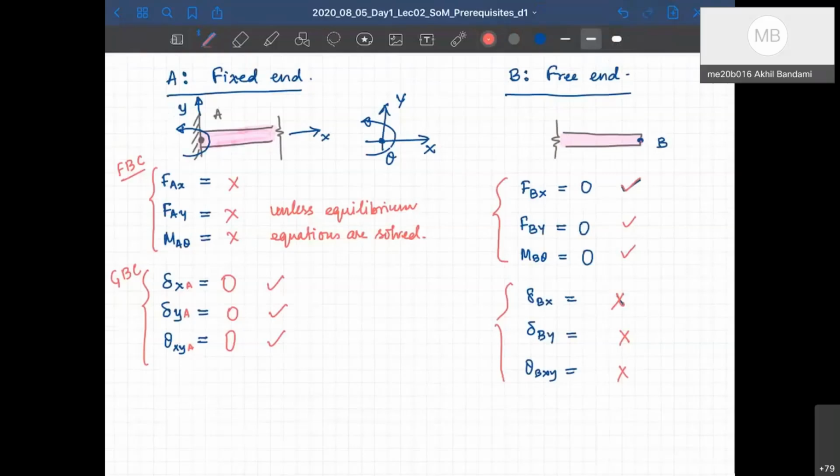Net force at point B, yes, it's 0, no? So then would there be some kind of internal force applied by the point just adjacent to B, to keep it in the rod? Yeah, you are very right. The point just before B will have some force, but not B. Because if you have some force at B, B is not going to transfer it to anyone. There is no one there, right? Correct. Unless there is another boundary condition here, B is not going to have that force.